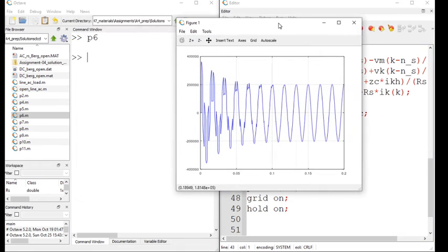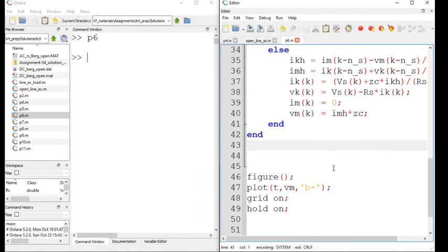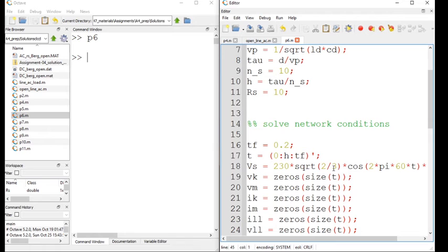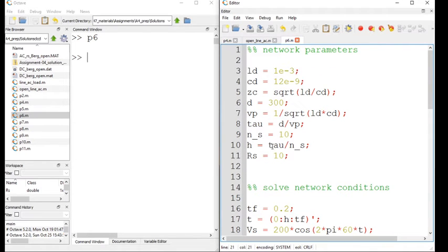This was the original thing which we did with simulation. Since we have chosen the voltage there as 200, let me change it appropriately here. We just set it as 200 volts there, isn't it? So we are choosing this to be 200, and let me remove the kilovolt thing, 200 volts. The rest is all the same except the time constant. Maybe we chose microseconds, and here it's of the order of milliseconds.